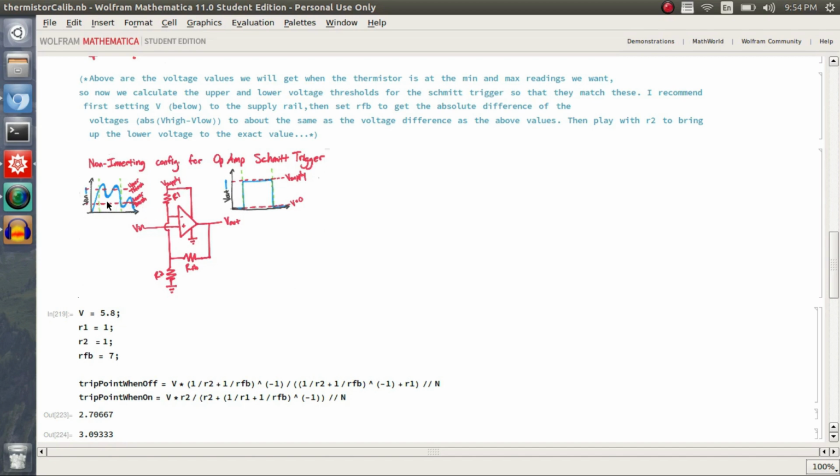And so then it doesn't turn off until... notice the blue curve can bounce below and above this upper threshold, but nothing happens, as shown in the output here. And then once it goes below the new lower threshold, it switches off. And then, of course, after it switches off, the upper threshold is set again to that value.